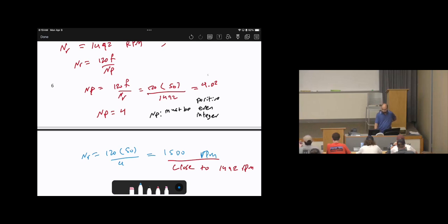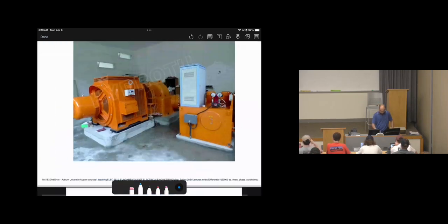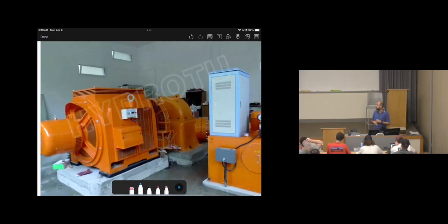Okay. Let's talk more about the calculation of the synchronous generator. Recall this graph, which we need to model into an equivalent circuit. We will assume this is 3-phase and balanced. Therefore, as we discussed in 3-phase, we will find the per phase equivalent circuit, right? Converting 3-phase to single phase. That's what we've learned before.